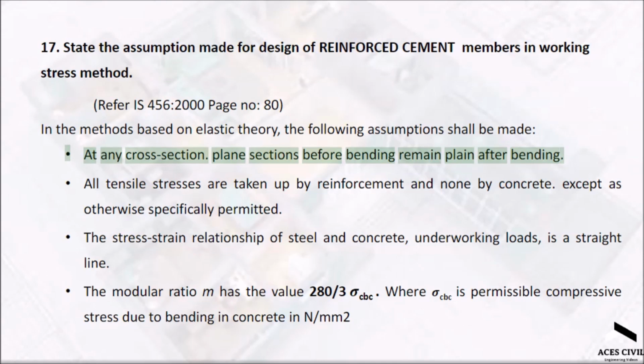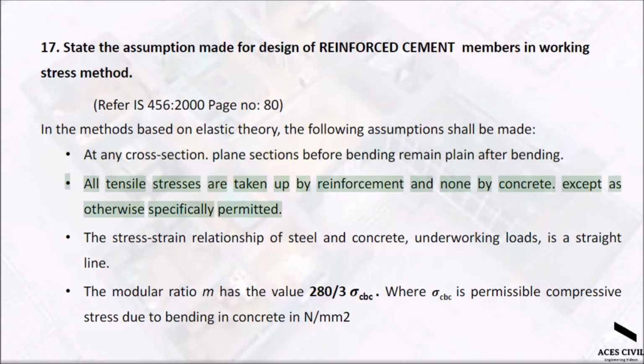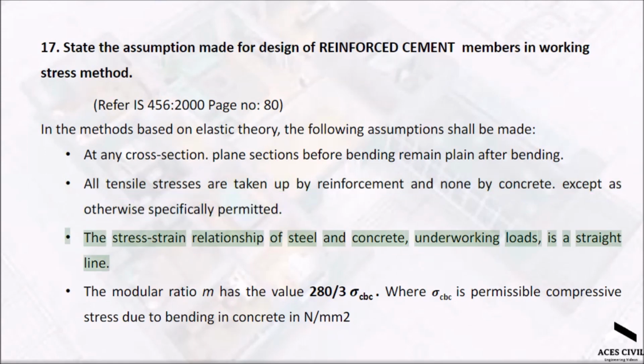At any cross-section, plane sections before bending remain plane after bending. All tensile stresses are taken up by reinforcement and none by concrete, except as otherwise specifically permitted. The stress-strain relationship of steel and concrete, under working loads, is a straight line.